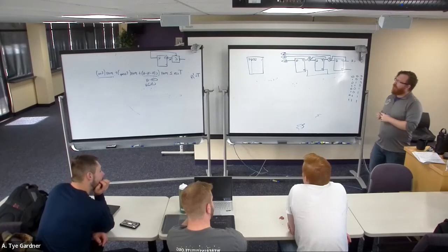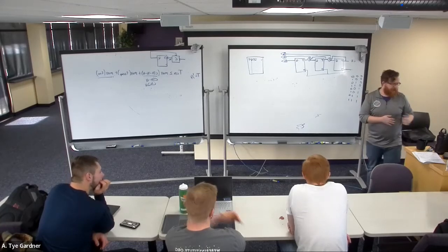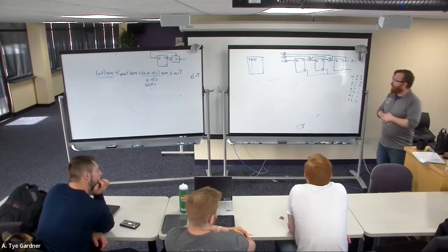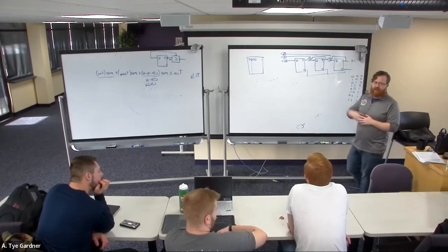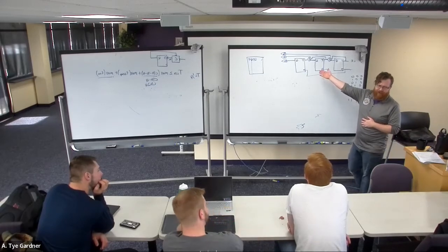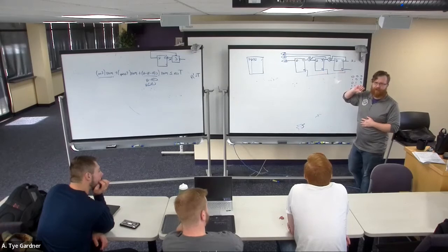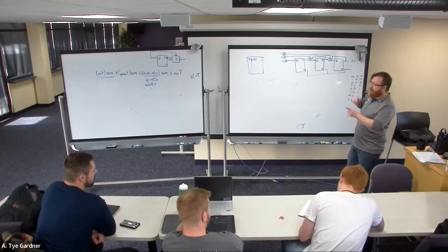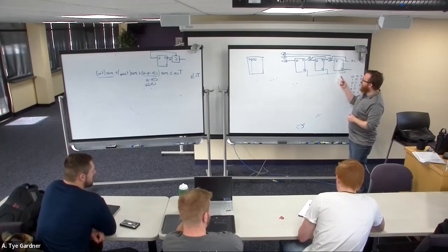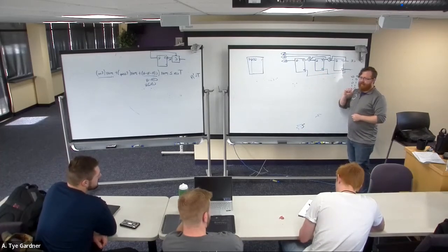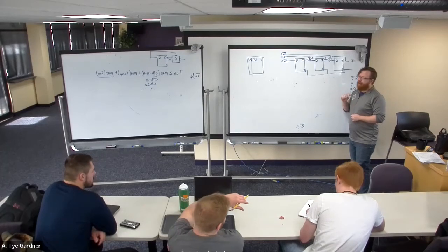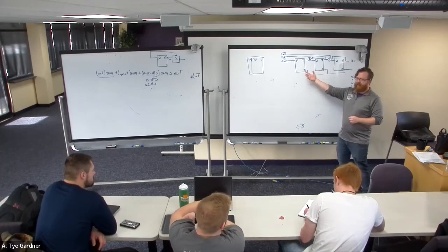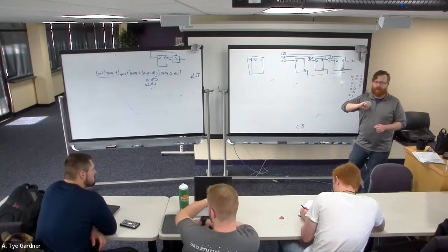And we'll probably come back to counters a little bit more to talk about them in depth because they're kind of interesting, which is this counter has an issue to it. Does anyone know what the issue is? Does it reset? Doesn't reset is actually a really good point in that it has to go all the way to 111 before it resets. So we could have little reset pins here and fix it. The issue is speed limit, right?